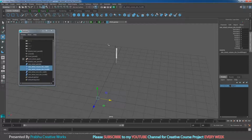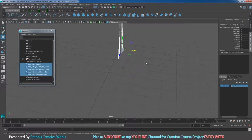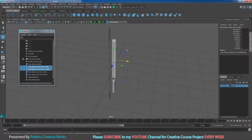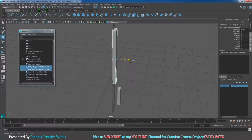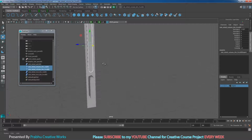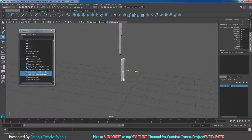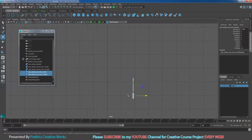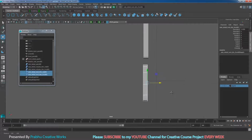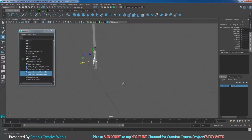Now I will select both objects. Select all these objects, go to modify and choose center pivot. I will select both objects and move in X over here. You want to keep it inside our mesh. Select both objects and move in X. Go to front view. Now I zoom in, you will be able to see whether it is perfectly aligned or not. Now go to perspective, see here.